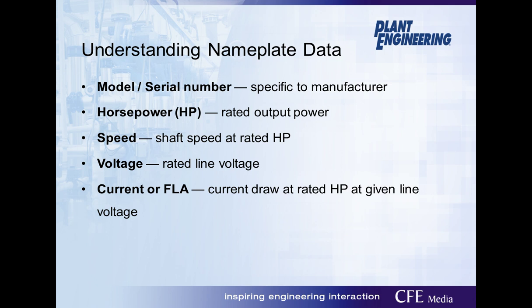I've seen many times in the past where a motor matched the basic nameplate data, such as horsepower, RPM, and voltage, and therefore it was installed in the place of a motor that was built for a specific application.